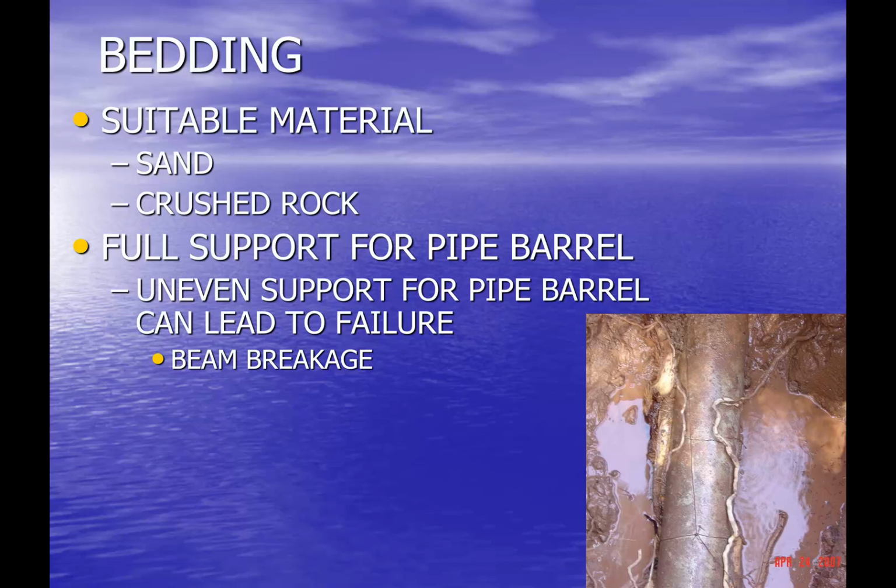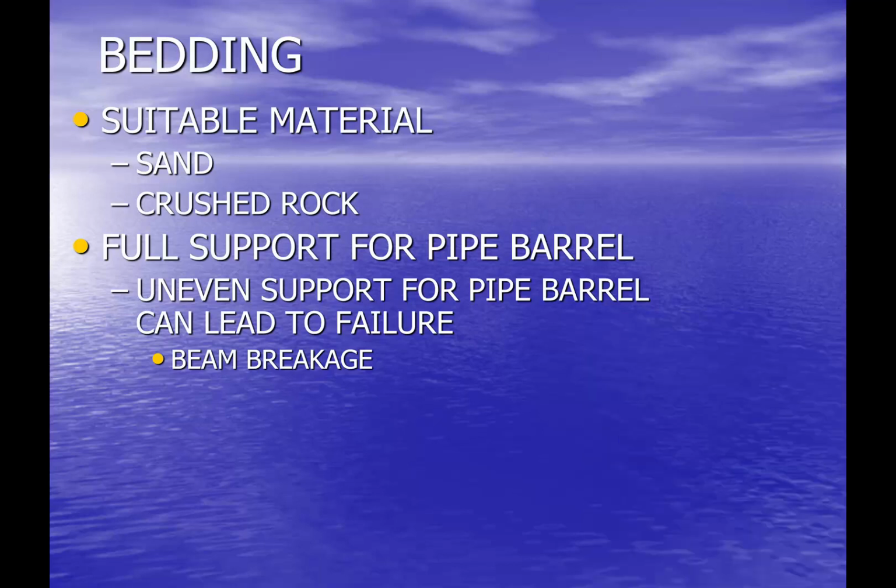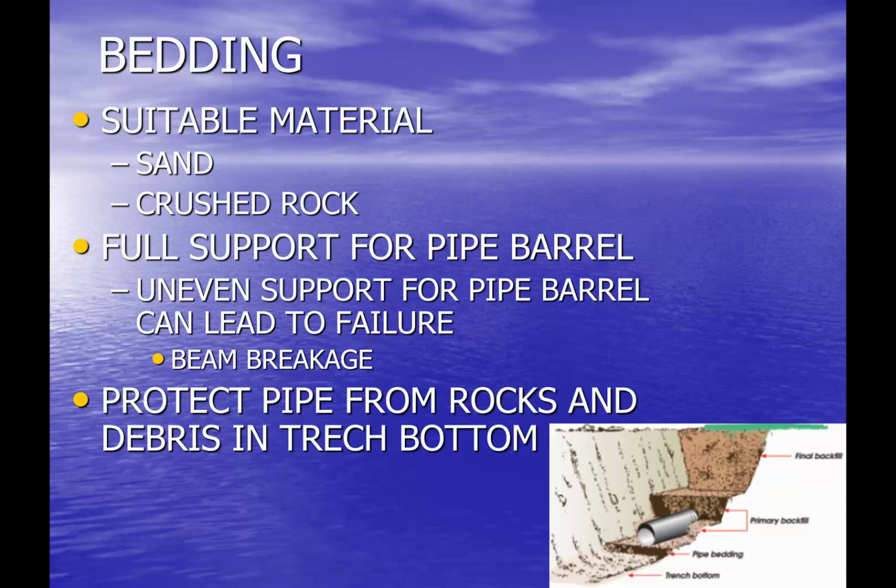Again, the material up over the top of the pipe between the bedding, and compacting that material, is what gives you really the full structural integrity of the pipe itself. As we said, the other important thing about the bedding is to keep rocks and any other kind of debris out. And when we get into the backfill section, I'll show you a good example of the kind of nasty material that can come out of a trench that we don't necessarily put back in, but we make sure that our pipe bedding is suitable to provide that support for the pipeline.